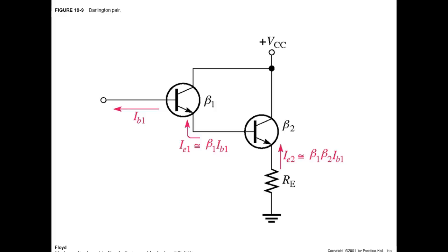Oh, we already talked about this. You okay? We call this what? Now read it up there in the fine print. We call this a Darlington pair. What do we use Darlington pairs for? So if I needed an extremely high input impedance, we can use Darlington pairs, and of course this would be a common collector.